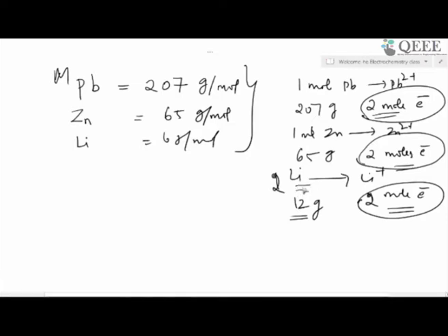Suppose you don't worry about the weight of the battery, that means for a stationary application, then you can go for the lead acid battery. But in addition to that, lead acid battery has some disadvantages. It has to be properly maintained. That means you should never allow the electrolyte to dry and never allow the cell to completely discharge. Okay. So these things you have to make sure, or you should not leave the battery in a charged mode for a longer time. For example, you charge a lead acid battery and leave it for 3 months and come back and try to discharge, it may not work, because of some other issues in the charged state.